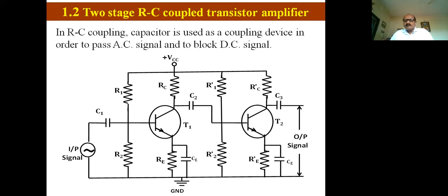Alternating current topic, first part. So, 1 divided by j omega C. As C increases, reactance decreases. Reactance is nothing but AC resistance, AC impedance. It is the capacitor's resistance to AC. Here the value of C is large, so the reactance is small and the resistance is small. Therefore high AC current can flow through this C, that means the AC voltage developed here can be passed through this C.